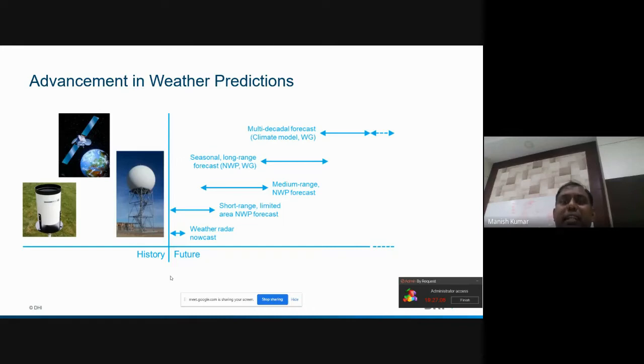Catchment runoff for the next few days. And when you route that water in the river, you have additional lead time, and that gives you how much flow in a river you will get in the next few days. So that is short-term to medium-term forecast. And then you use various statistical tools and other methodologies to calculate seasonal or long-term forecast.